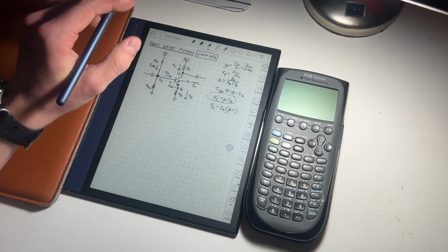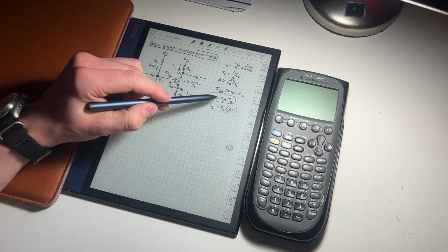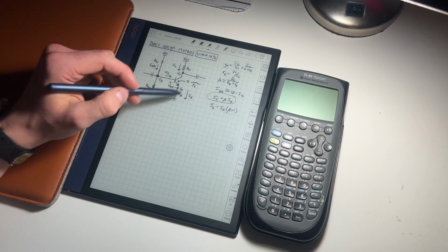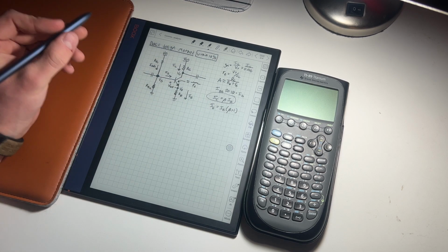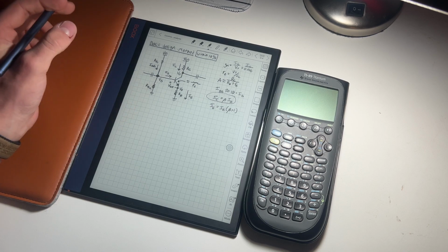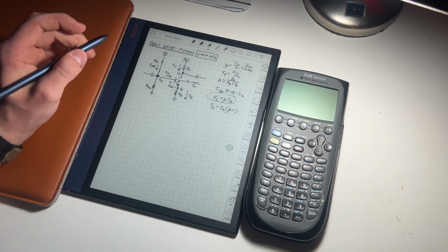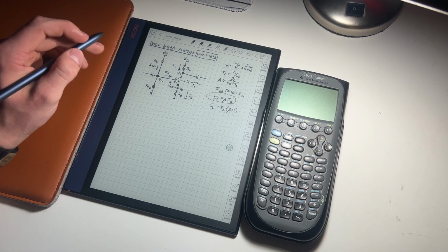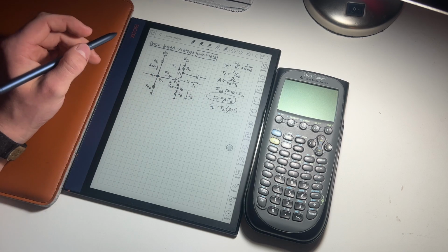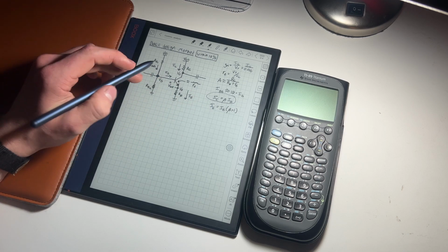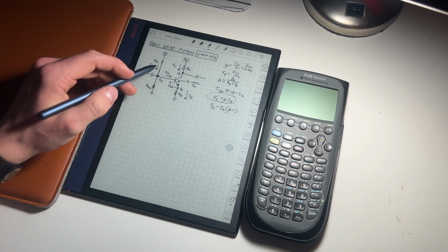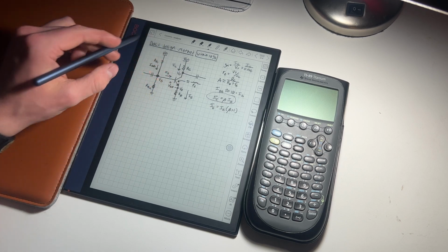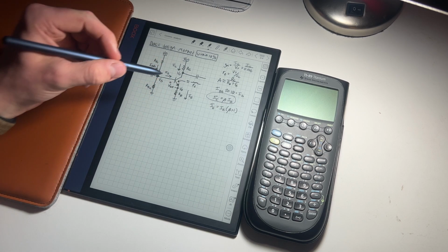And when we go into LTSpice, I will show you guys the same amplifier setup with a completely different transistor with a beta that is much less or much more. And you'll see that as long as your current gain is sufficient in that transistor for the gain that you want, the gain output of the whole circuit will always be around what you want.